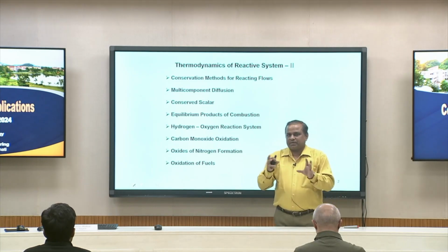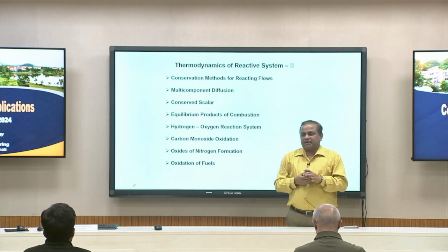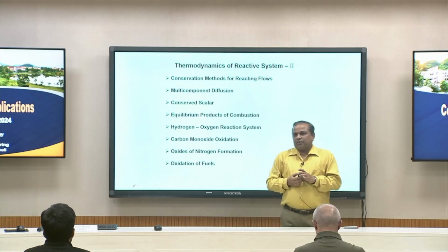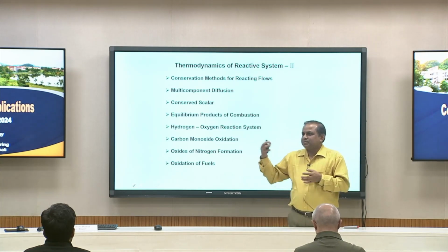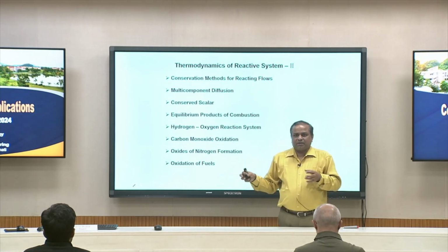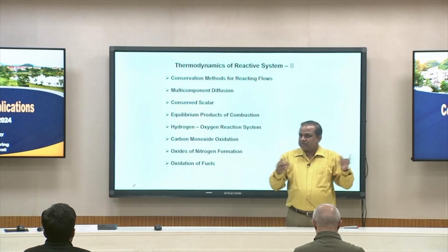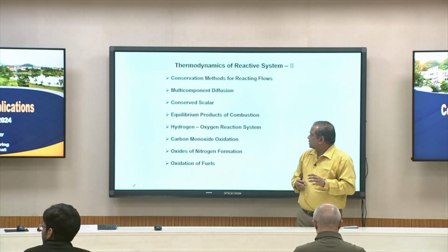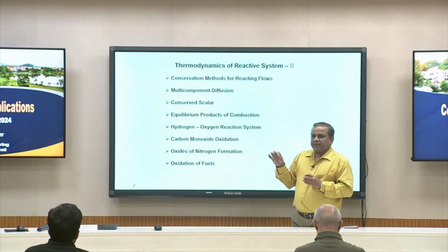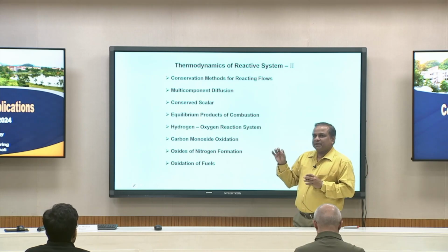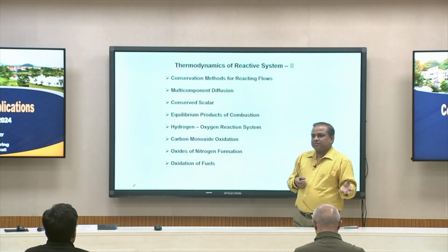It changes drastically. In some zones the fuel is completely rich, in some zones the fuel is completely lean, because they are not mixed properly as per the stoichiometric conditions. So in such cases, what is the criterion by which fuel retains its identity? When it is pre-mixed, fuel retains its identity through the value of equivalence ratio. We say it is lean or rich.